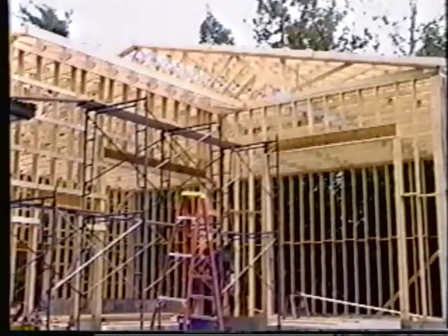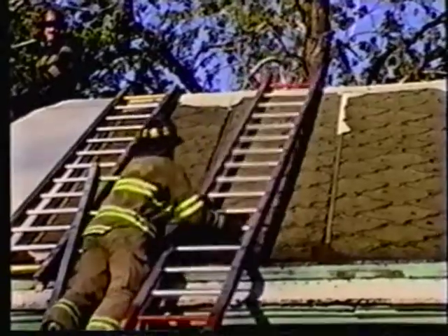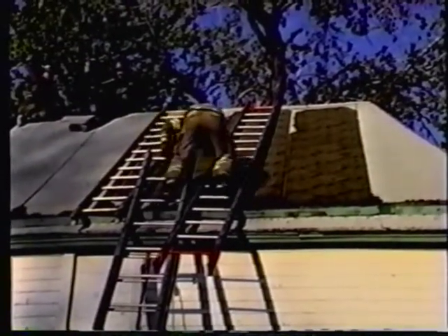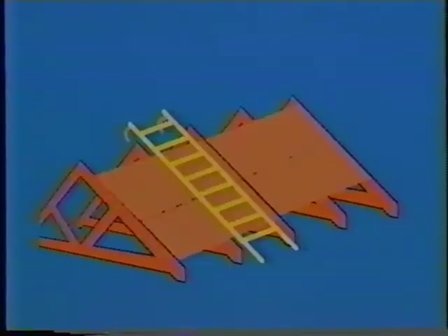Beware that on lightweight wood truss construction, roof ladders are not a safe platform to work from. Roof ladders are designed to span the roof surface from ridge pole to outside wall. The theory being, if the decking collapses, the ladder still will be supported by the ridge pole and the outside wall. But in truss construction, there is no ridge pole for the ladder hooks to engage. The ladder is supported only by the roof decking and therefore will collapse with the roof decking.